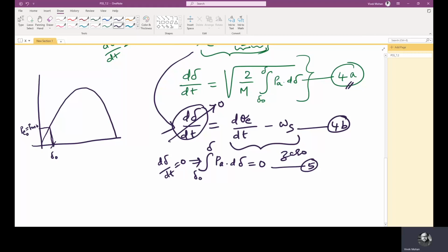Now, if from the equilibrium point corresponding to δ0, Pe0 and Pm0, there is a sudden increase in input mechanical power, initially it is Pm0, now it is moved to Pm. Corresponding to Pm, there is another value, let it be δ1. Now what is the importance of this region?